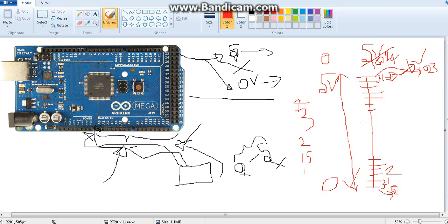In case you are giving 5 voltage from the sensor, Arduino will take this 5 voltage and keep it with its scale, and it will realize it is 5 voltage, so it will fill up all these 1024 spaces. The value will be from 0 to 1023, every unit will be filled. So Arduino will consider this 5 voltage as 1023 analog units. Forgive my writing because I am using Paint, so it may not be clear, but just follow my voice.